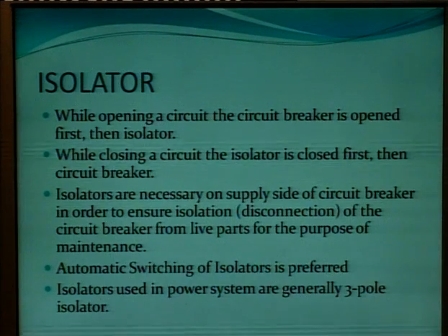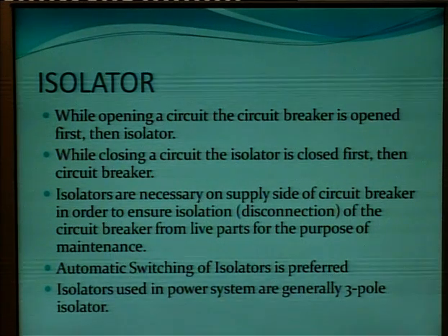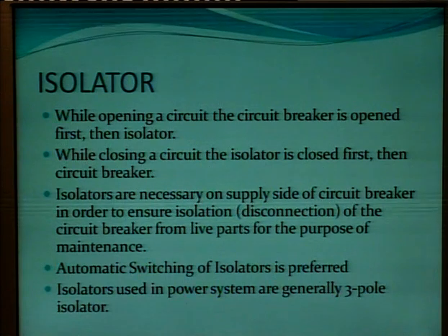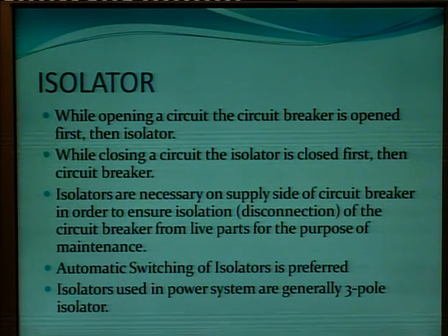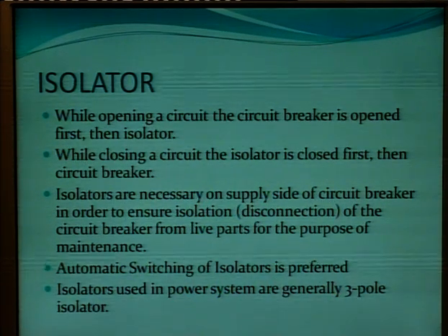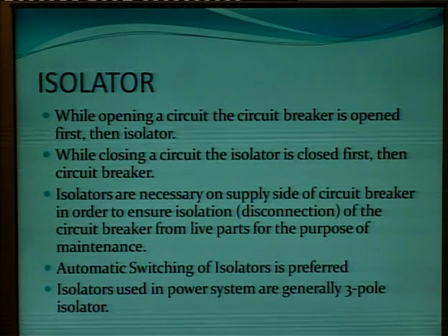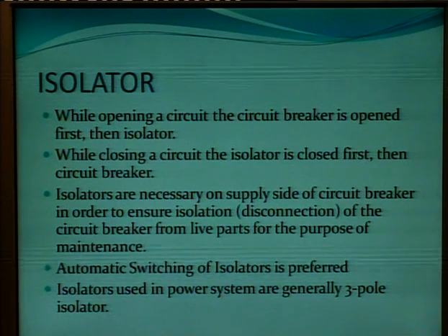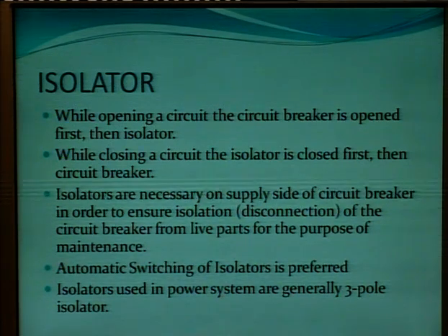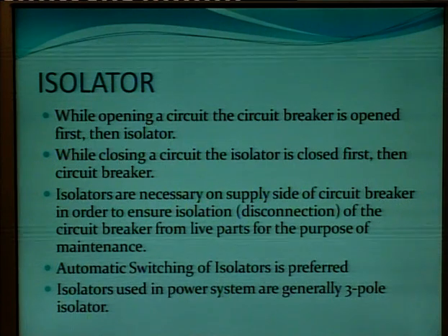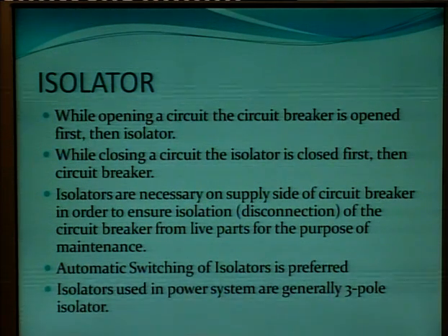Isolators are necessary on the supply side of the circuit breaker in order to ensure isolation of the circuit breaker from live parts for the purpose of maintenance. Automatic switching of the isolator is preferred. Isolators used in power systems are generally 3-pole isolators.